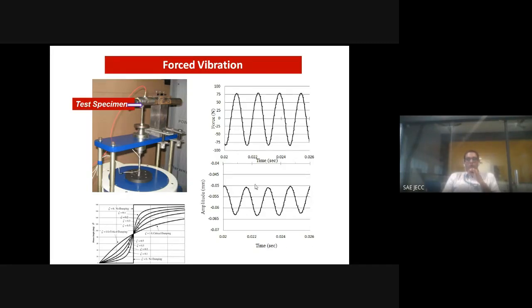Observe these two. You can see that one part is starting from this extreme end, and this one is from the other end. That means there is phase difference. That means you may be pushing the system by the time the system may be moving down. So this is a very interesting phenomenon. The phase difference between the force signal, that is the excitation signal, and the response signal gives the nature of the damping that happens in that particular system.